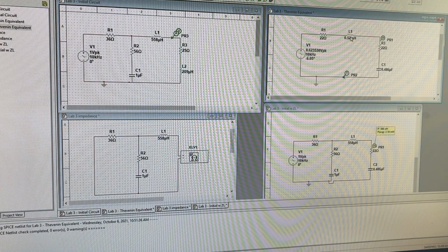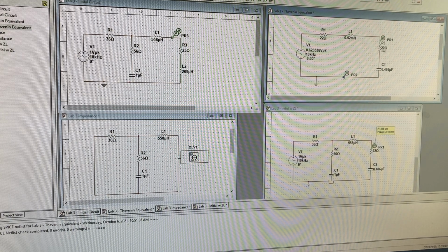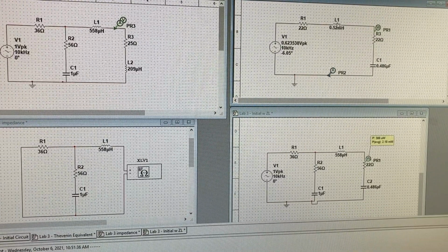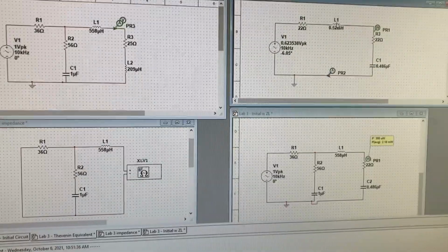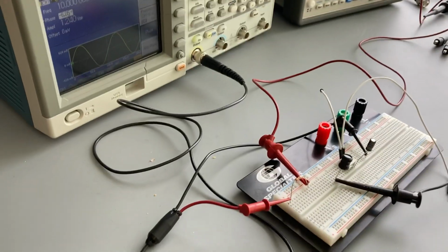So I add those components in, based on my reactance and based on the resistance that I needed, and I change my voltage values, change the phase, and then here it's the complex conjugate. This real value is the same in both cases, but this is the negative value. This is the inverse value of what I got for this inductor. And so basically we recreate that circuit